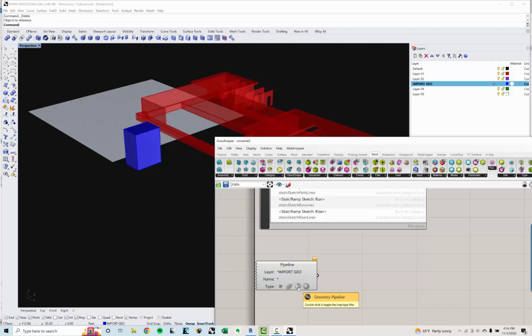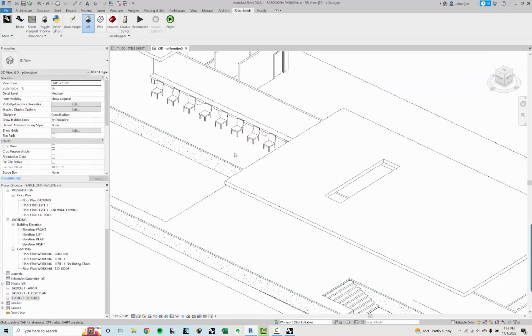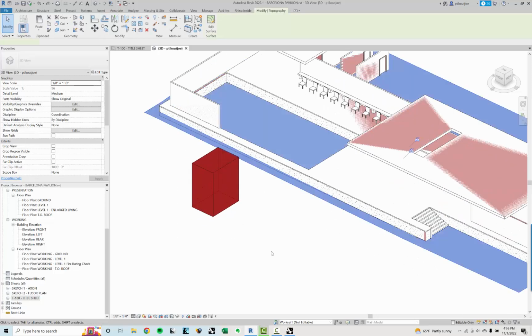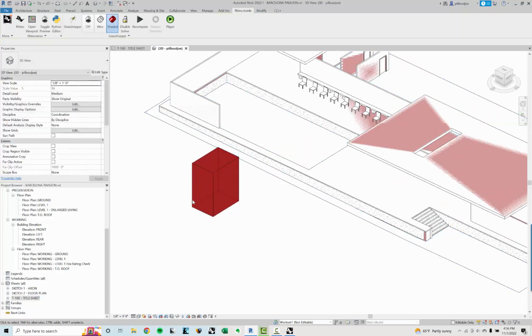And then down here, I want it to be a BREP, a boundary representation. I only want my solid geometry. If I'm building curves to kind of help me construct things, I don't want those to come in. So I'm going to click on that. And then if I actually click on geo, there it is. Now, I think this will show up in here. Yes, it'll show up here, but not as something that I can select. This is just a way for me to quickly bring things in.